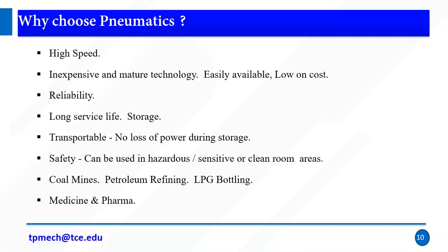Medical and pharmacies, medicine and pharmacies. So generally the packing of medicines is done by pneumatics, because if you use hydraulics, it may leak. Hydraulic fluid has chemical content, so it may react with the medicine and it will be hazardous to humans. So in medicine and pharmaceutical applications nowadays they use pneumatics, right?